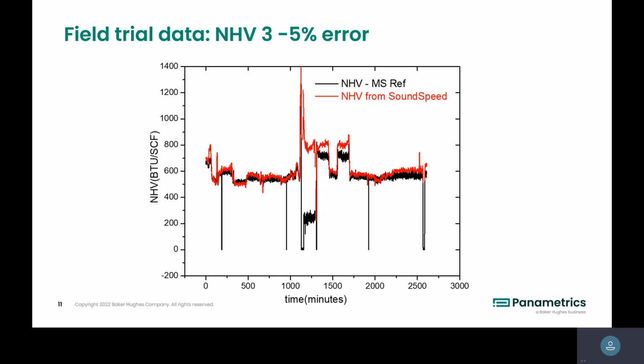This data is from a customer who is actually using Flare.IQ, and they also have a mass spec measurement. The mass spec, for example, has a drop about every 24 hours. I talked to them and they said it could be because of calibration. The mass spec usually provides two channels, but they only take one channel reading, so when it goes into calibration, the reading goes to 0.